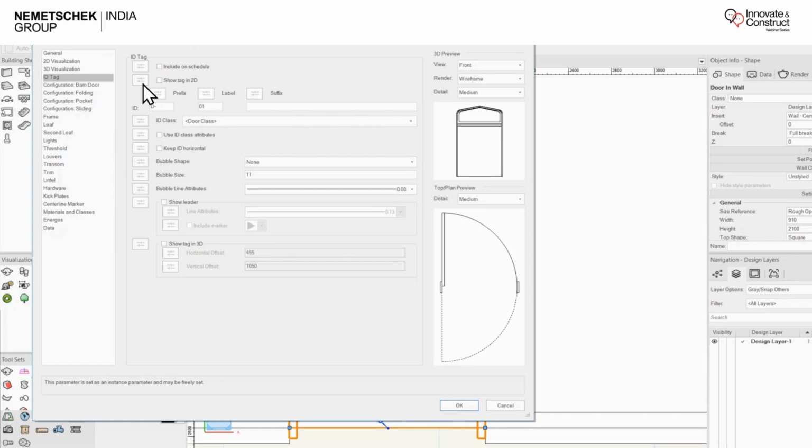So you don't need to remember, or there is a tool called Tag All, which will define all your tags, and you just have to click it. So you can customize D1, D2, or whatever you want to call it as per your standard. If you have a company with specific names and project standards, you can use them, and this will save your style.